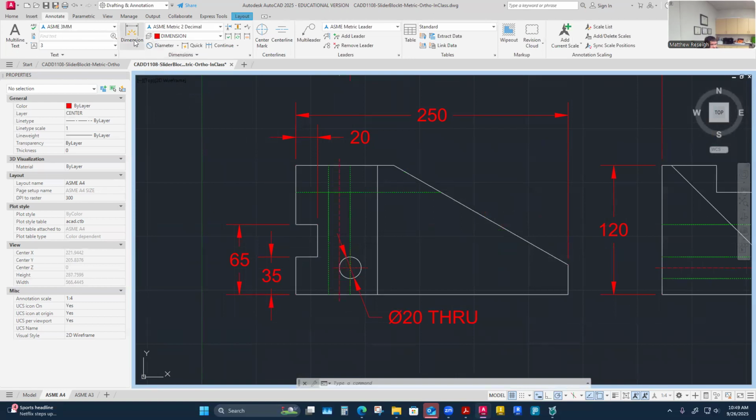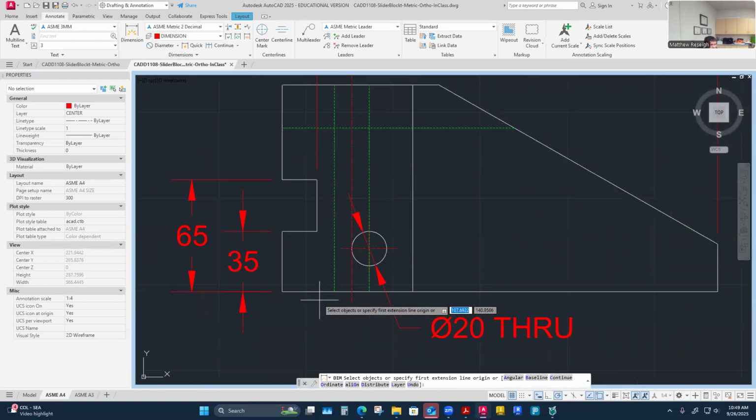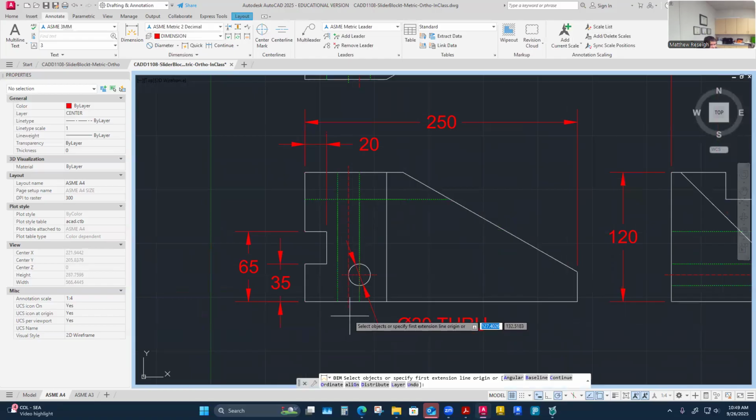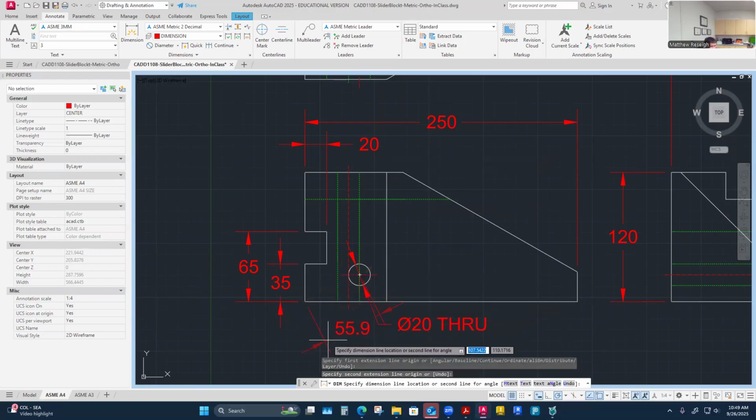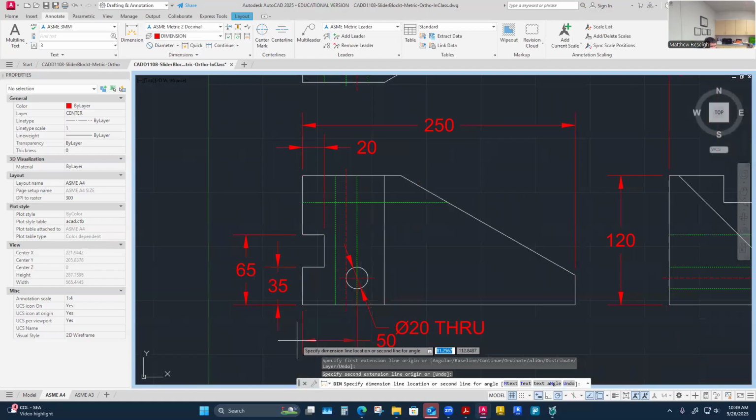So that's the size. Here's the location, it's going to be from some datum over. And I think I'm probably going to pull from this. I mean, we're kind of establishing a pretty hard datum with this, even though it's the left side. It's kind of lending itself to me. I'm using the bottom surface where it appears as a line as kind of a datum here. I'm going to start using this left side as a datum. I'm already using it there. So I'm going to say this one to the hole center, right, is going to be one of the location dimensions.